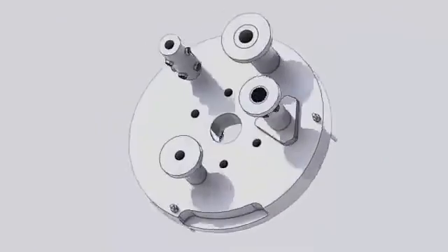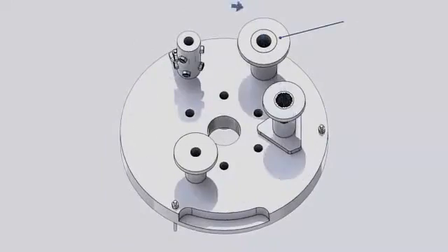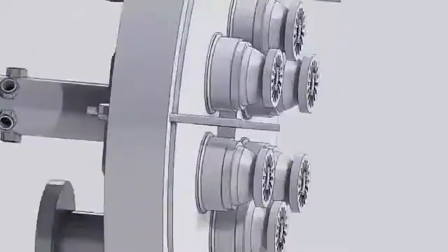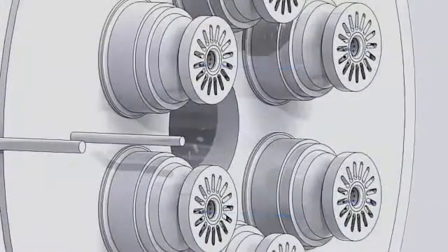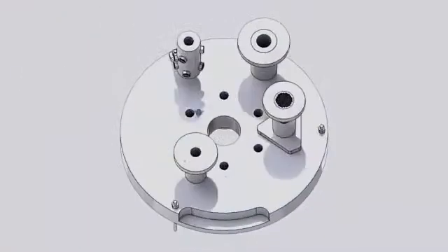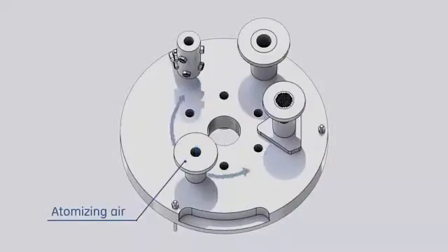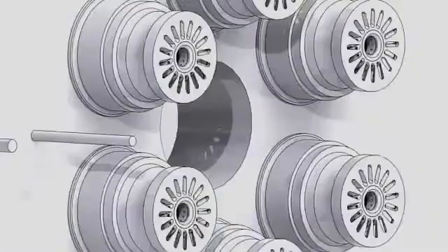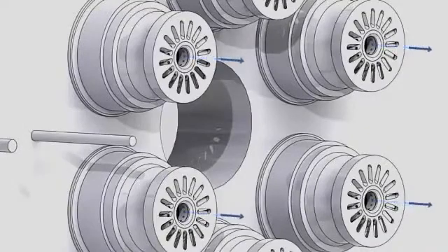Gas fuel enters the primary nozzle's assembly through the fuel gas connection flange and is routed through internal machined passages to the orifices located in the gas tips. Atomizing air is introduced in the same manner through internal passages and exits to the primary zone through multiple holes on each of the gas tips.